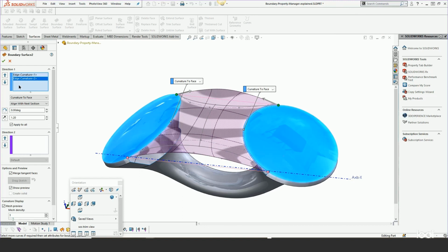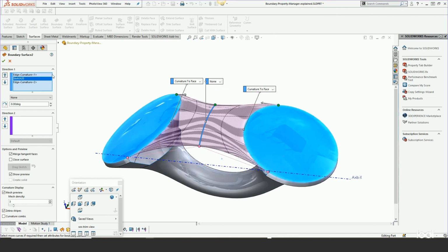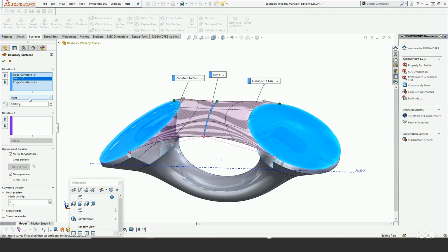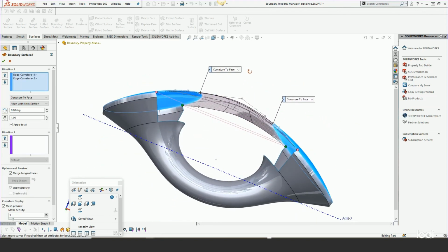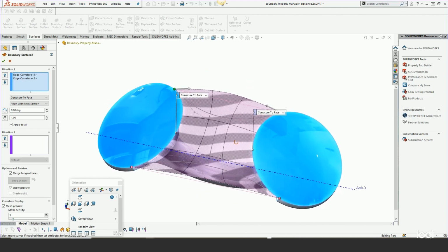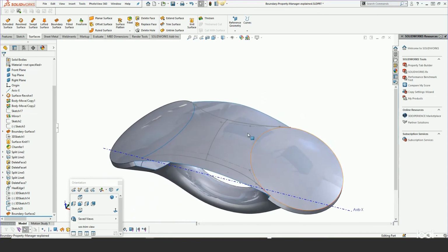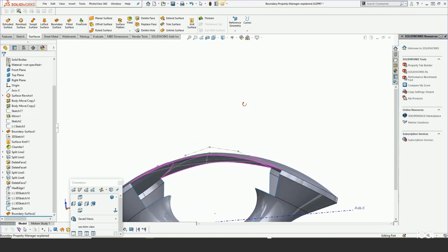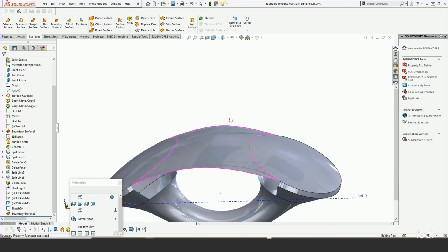And that really is better highlighted when you have this curve right here. So unfortunately, when you do include that, the option goes away. So this could be an acceptable surface, and it does rebuild. So it's just nice that you get those various options to get different solutions, and you can actually control how the surface is flowing and what it's matching when you create this boundary between these two.